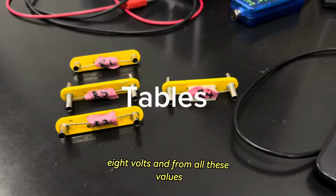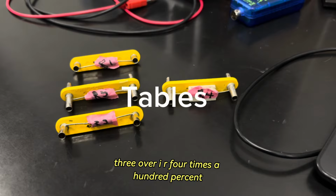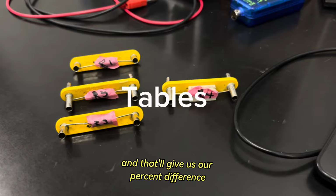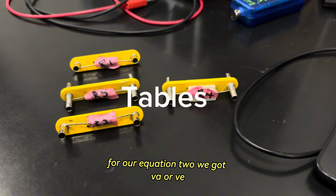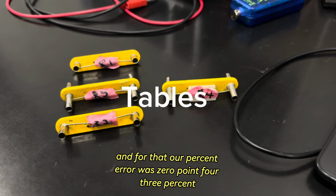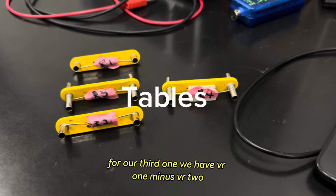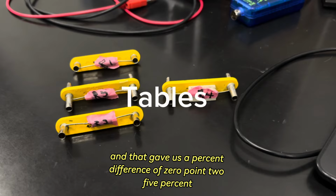And from all these values, we have three different equations. The first equation is IR4 minus IR1 plus IR3, over IR4, times 100%. That gives us our percent difference, and with this we got a 0.79% difference. For equation 2, we got VE minus VR1 plus VR4, all over VE, the absolute value of that, times 100%. For that, our percent error was 0.43%. For our third one, we have VR1 minus VR2 plus VR3, over VR1, times 100%, and that gave us a percent difference of 0.25%.